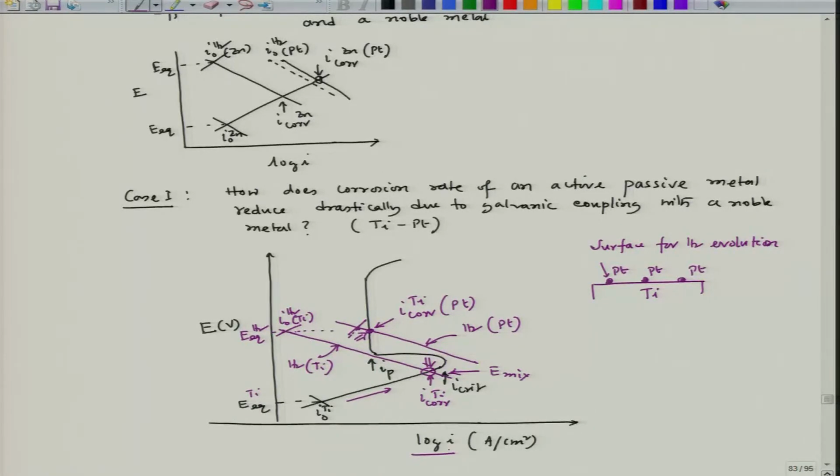Fine. So, now the question is, how do we have platinum enriched regions or local spots on titanium? For that it is a kind of smart move, I would say. We alloy titanium and platinum, and the platinum would be a very small amount. Now, if this particular alloy is exposed to an electrolyte, titanium can dissolve preferentially, because the titanium is very active compared to platinum.